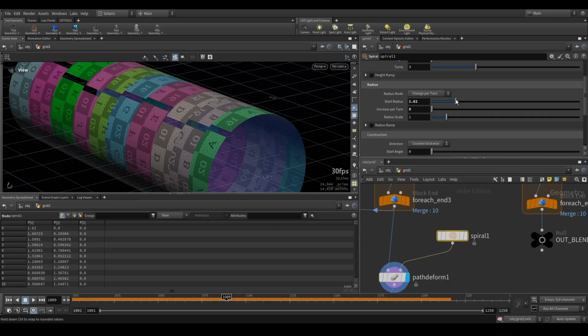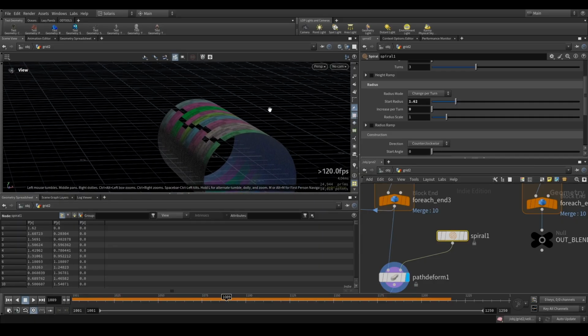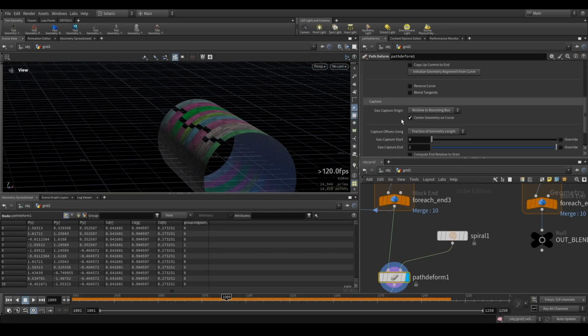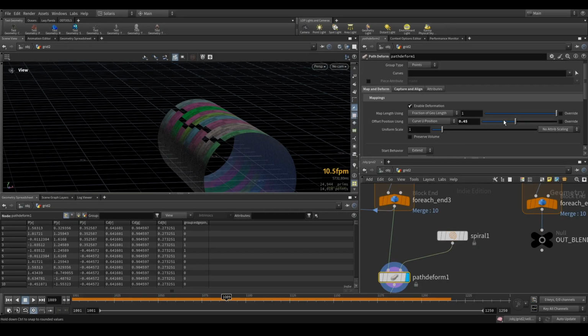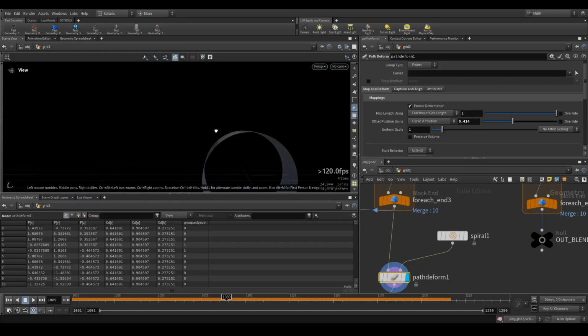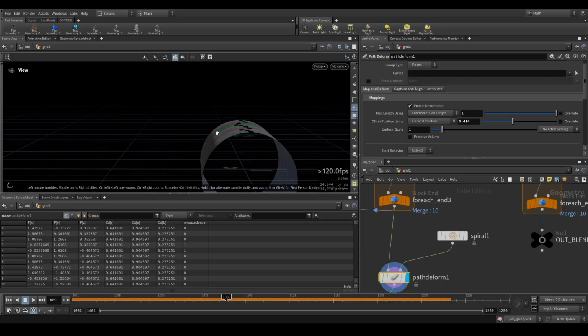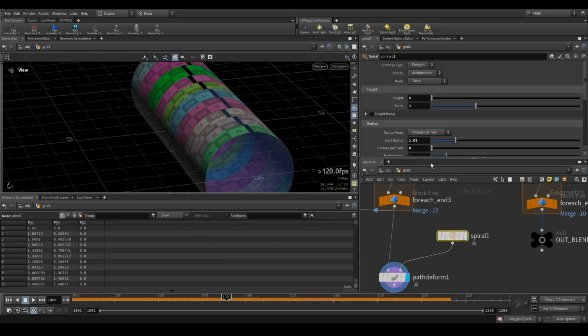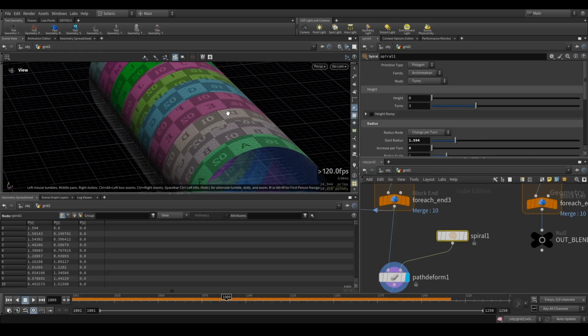Let me open it up a little bit again, because I want this seam to be at the top. So for that we can use this offset I was mentioning before, and we can pivot a little bit. And this is fine, this is top enough for me. So I'll fuse it back together, not fully, so I can see a little gap here.